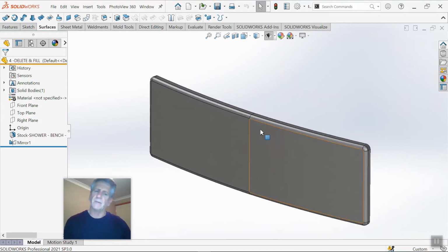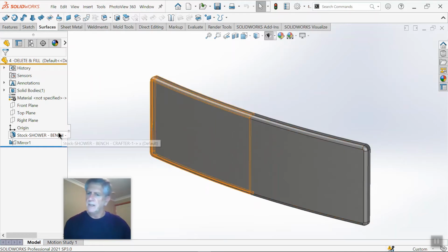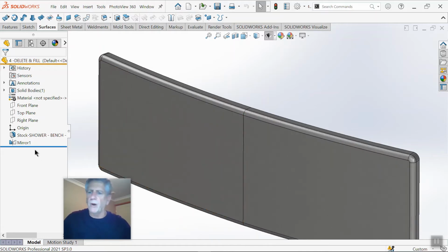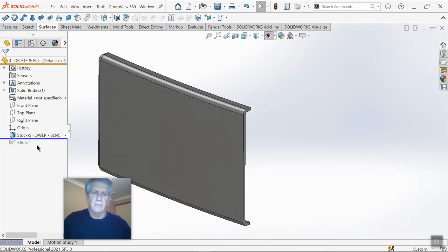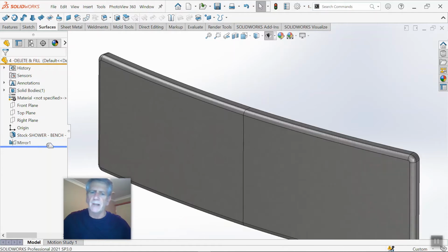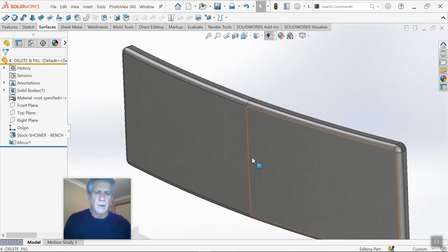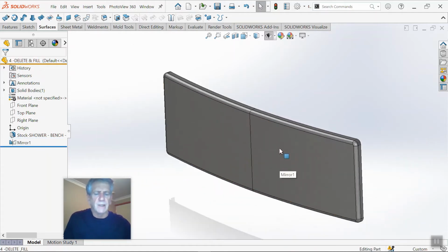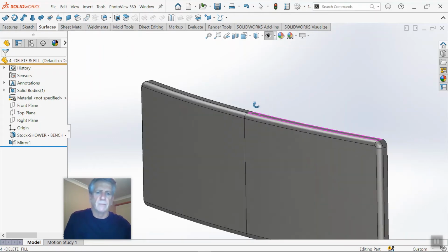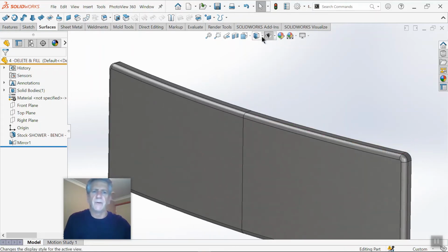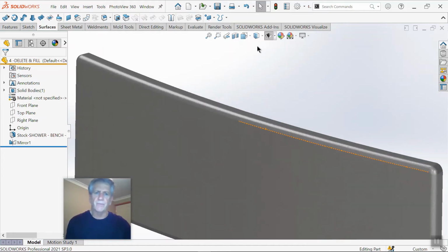It's a face of a drawer. It, again, has been used as an insert part somewhere along the line, and it's been changed. We would have cut it, and then we've mirrored it, and we end up with this line. And while it's not a huge tragedy, I guess we could just display it as tangent edges not shown.